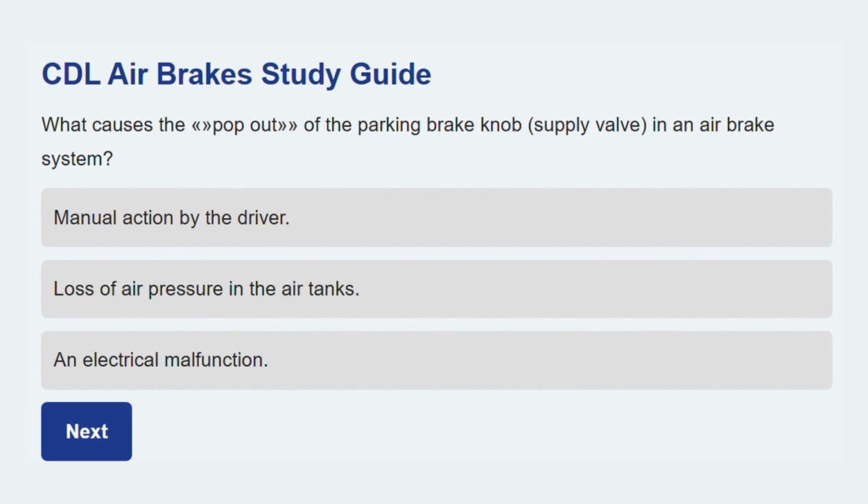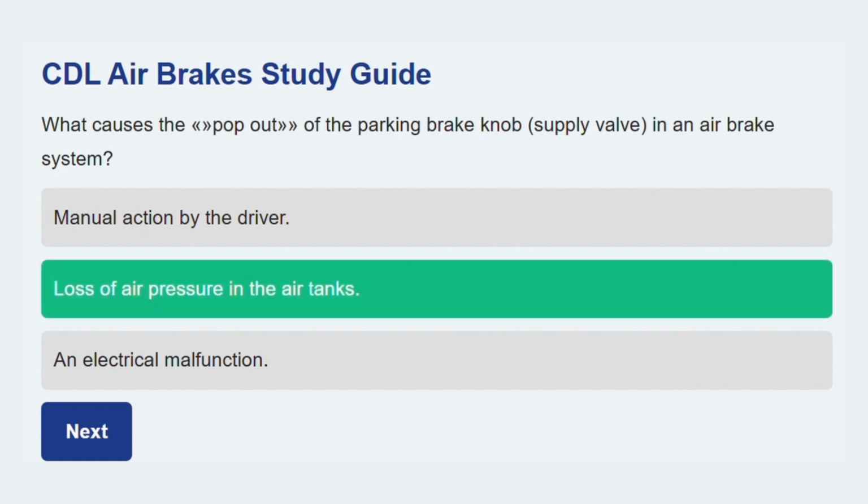And the next point, what causes the pop out of the parking brake knob supply valve in an air brake system? Loss of air pressure in the air tanks. When the air pressure drops below a certain point, the spring brakes engage, causing the knob to pop out.